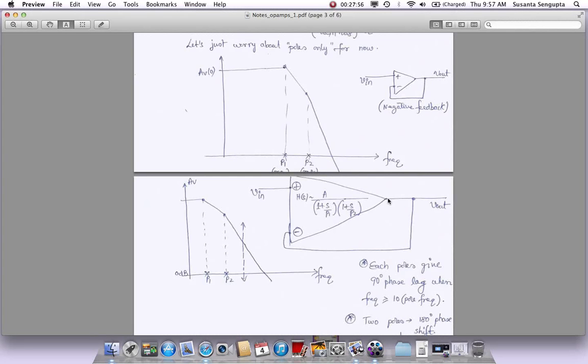What happens in a positive feedback system? If I had an op-amp like this, and just one single frequency component at the input, because of positive feedback, it will start growing bigger and bigger and bigger, and it will start to rail, it will start to saturate. It will saturate this guy, or cause large oscillations at the output at that frequency component, or even any other frequency component.